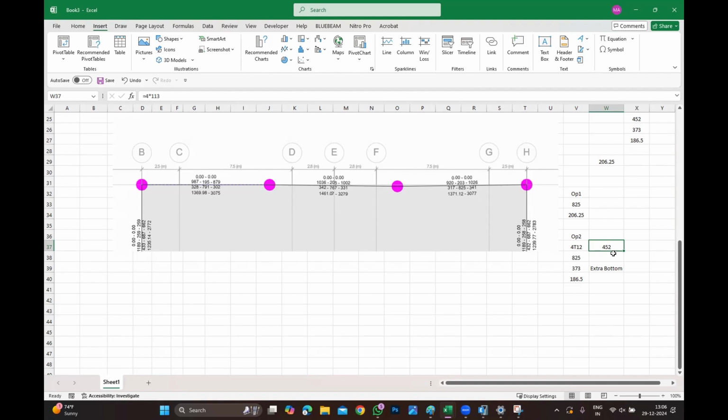Here we are talking about 4T16, right? You can go for it, but keeping the 400 millimeters, at least minimum, keep 4 rebars. If you keep 3, then it looks like the space is huge. For 200, you keep 2 rebar. 250, and in some cases, I can accommodate 3 as well, if the diameter is less. And 300, 3 bars. 400, 4 bars. Keep it, actually, for practicality, so that you did not make any kind of mistakes.